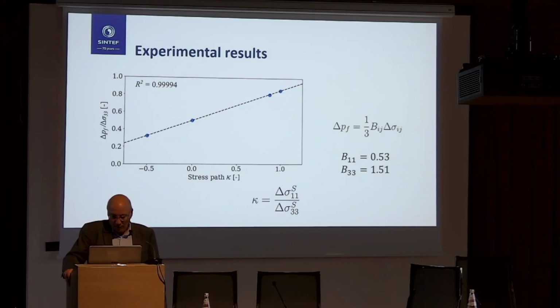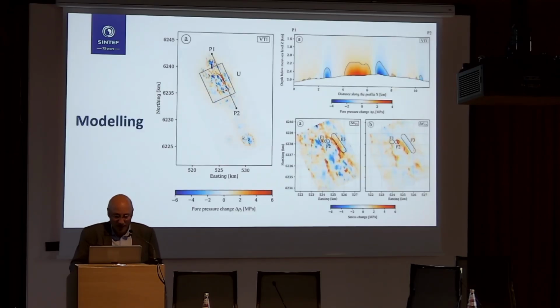So a possible reason why these data points are so aligned is that maybe the sample was loaded a bit too much before the cycles shown in the previous stage, and it was already plastically deformed. Then it was unloaded, and the 4 cycles are within its new extended elastic range set by the first, accidental loading. We don't really know, but when we have nice results, we tend to accept them.